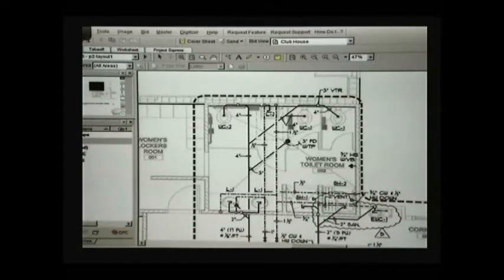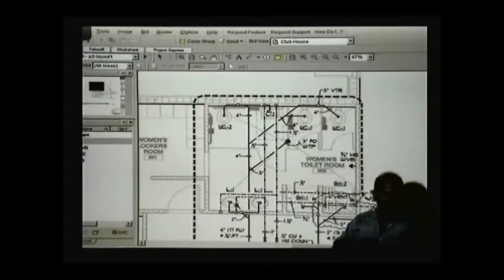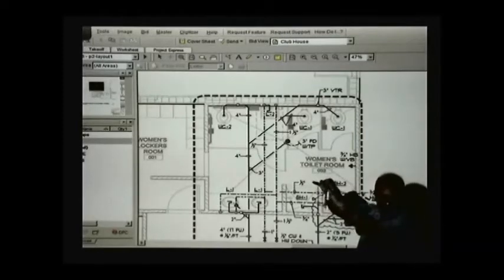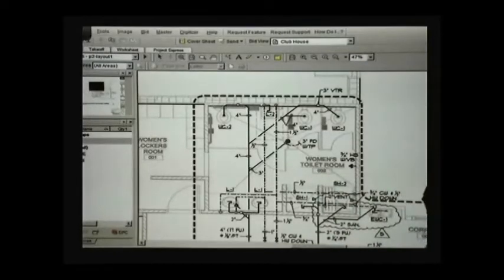The other thing with these pipes is that, remember we talked about two different systems. One is pressurized water, and the other one works with gravity. The drain vent system works with gravity. So what happens is that you need to have ventilations that go all the way to the roof for this system to work. It's like when you have a straw, you put it into water and you hold the end, the water doesn't move because it creates a small vacuum over there. So you need to vent that out in order for the water to move. Same principle goes with the wastewater system.